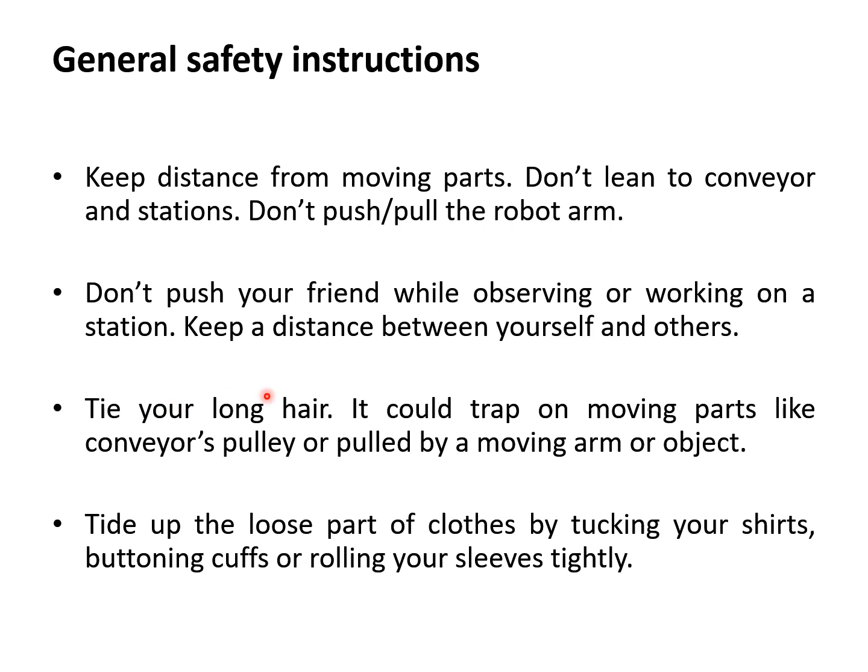Do not push your friend or colleague while observing or working on a station. Keep a distance between yourself and others. Tie your long hair. It could get trapped on moving parts like conveyors, pulleys, or be pulled by a moving arm or object. This is specifically important for those who have long hair, either men or women, doesn't matter.